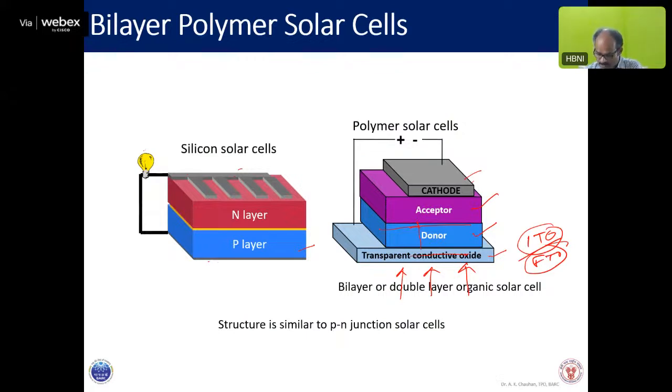However, there are a lot of problems in this. As I said in the slide on the difference between inorganic and organic semiconductors, it has very poor mobility, even if electron hole pairs are generated at these two points. It is very difficult. First thing is they are excitons now. It is not a single crystal. The entire block is not a single crystal, so they are localized levels.